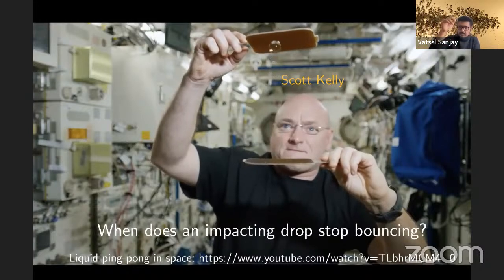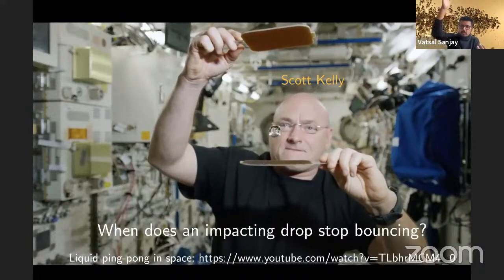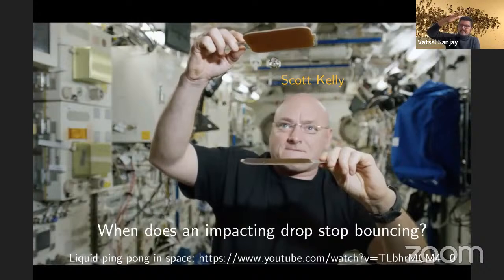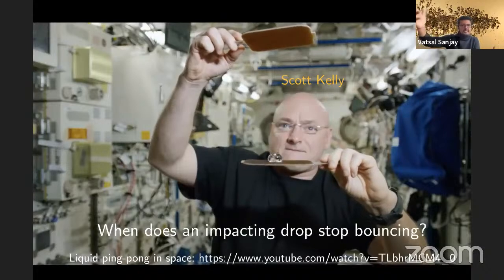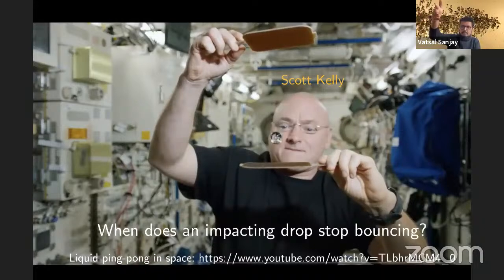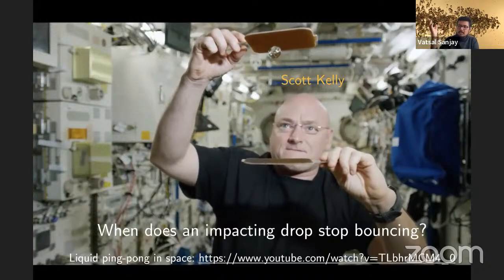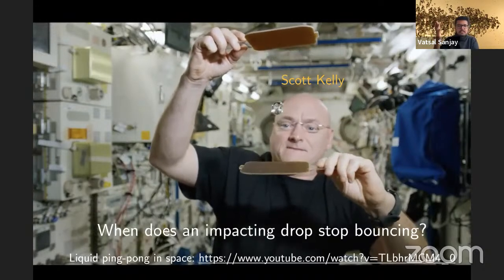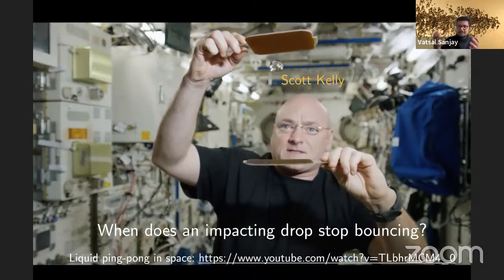For the same set of things that we are trying to do here, which makes me wonder whether the limit that we find, this Ohnesorge of 1 and Ohnesorge plus Bond equals 1, really is the upper limit if you were to have a perfect super hydrophobic surface, which doesn't exist. I mean, theoretically it exists, but if you assume that this air layer is stable enough that it doesn't go anywhere, it's always there, then you would get this upper bound that we find. But there are works in the literature where the hydrophobic surface is not good enough, and then the critical Ohnesorge number is not 1, but even 0.2 or 0.5. So we numericists try to avoid those.